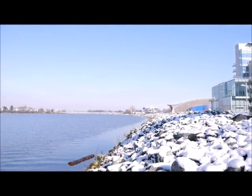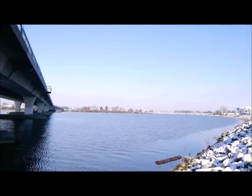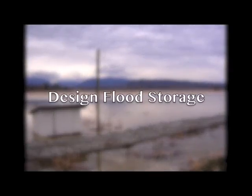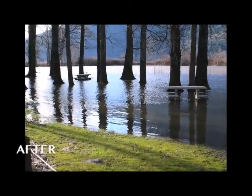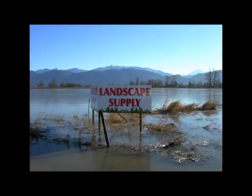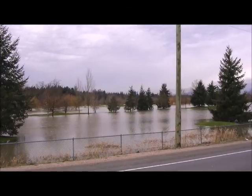Given increased climatic variability and densification of urban landscapes, additional measures need to be considered. An innovative approach to flood protection is called design flood storage. This is where we designate topographic depressions within the watershed as a place for temporary water storage during very large storms. Areas with minimal building infrastructure, such as playgrounds, parks, golf courses, and agricultural areas, can effectively serve to temporarily store water that can be released after the peak storm has passed.